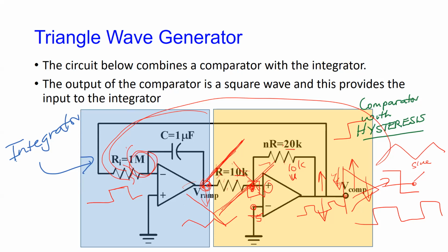When you turn that dial, what you're changing is this resistor. If I put a variable resistor here and vary it, I'm able to vary the frequency of the oscillator, and I could get a variable frequency triangle, square, or sine wave coming out of it.